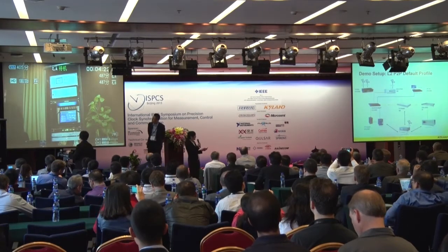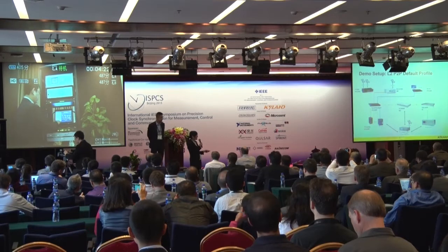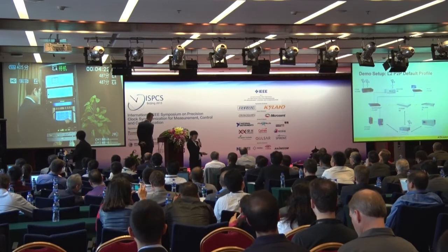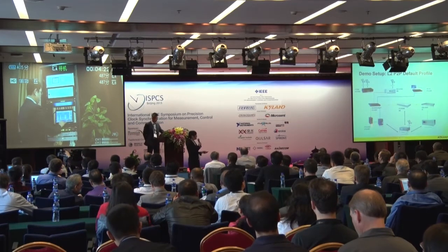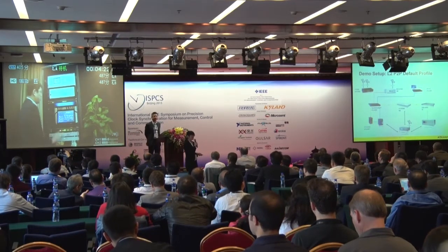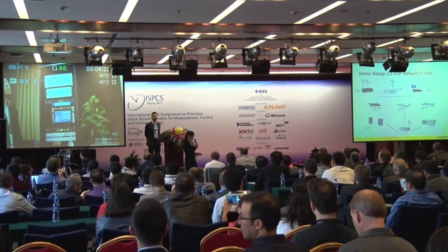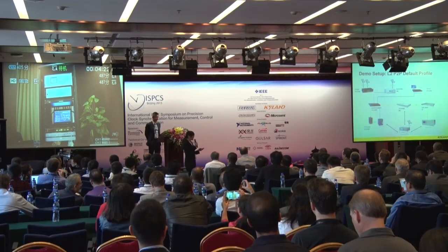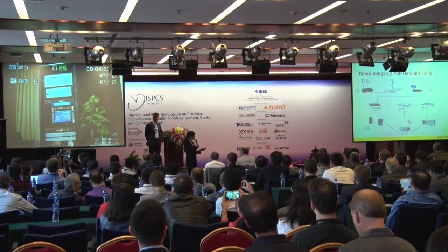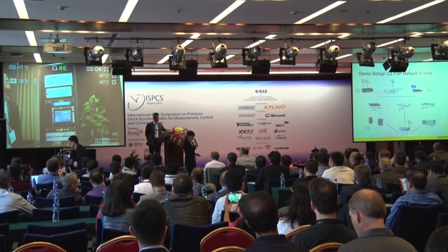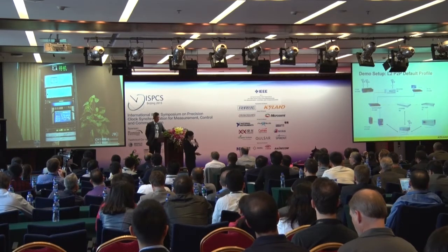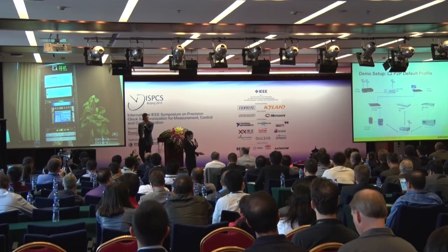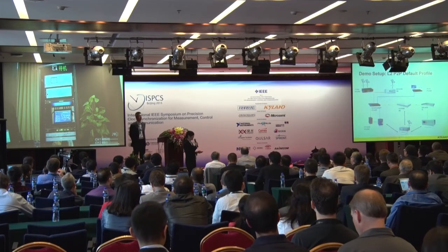And we have 2 different protection relays. One protection relay is synced with IEEE1588, and the other protection relay is synced with IRIG-B, which is converted by a time converter from IEEE1588 to IRIG-B. We're using a time tester to test all the different time signals in the system to check the accuracy of the system. And we are also using a TMS system to monitor the whole time system.